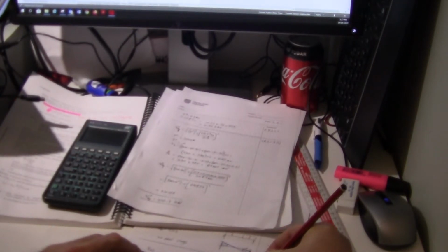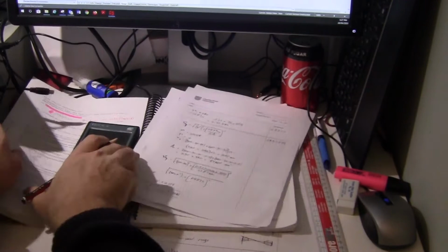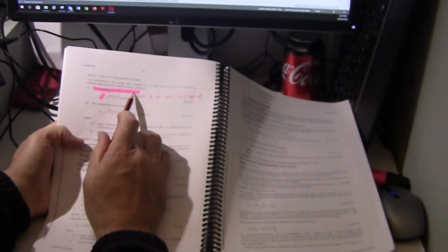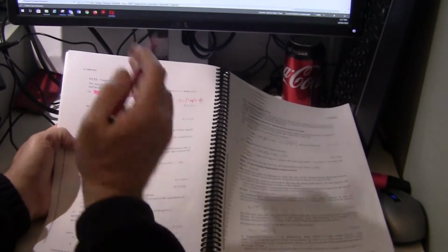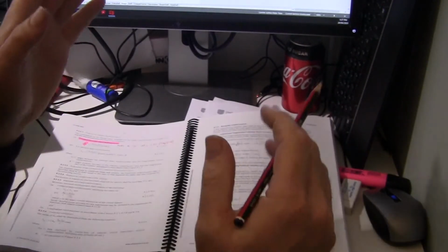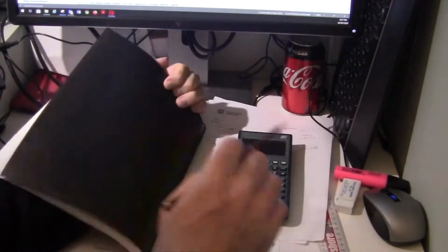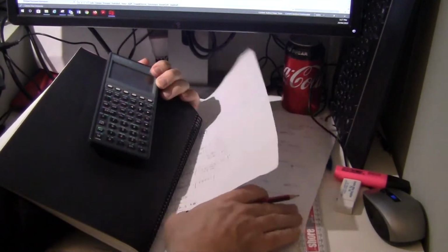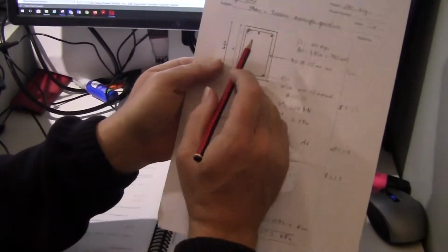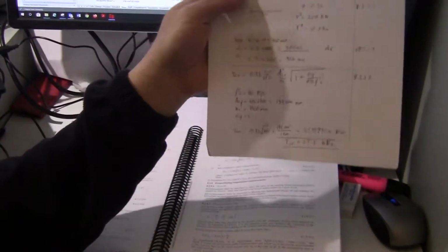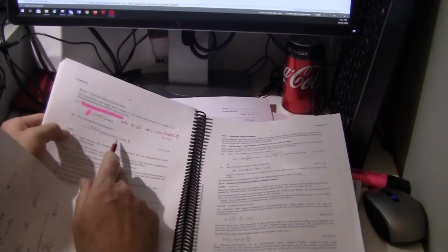Clause 8.2.5.2. For perpendicular shear reinforcement, for inclined shear reinforcement. The vast majority of times you build with concrete, you put the shear rings at 90 degrees, that is vertically across the beam, and that's how they work. If you're trying to be clever, you can tilt those rings slightly, and if you tilt them the right direction, you get some additional capacity. That's what this comes in here.